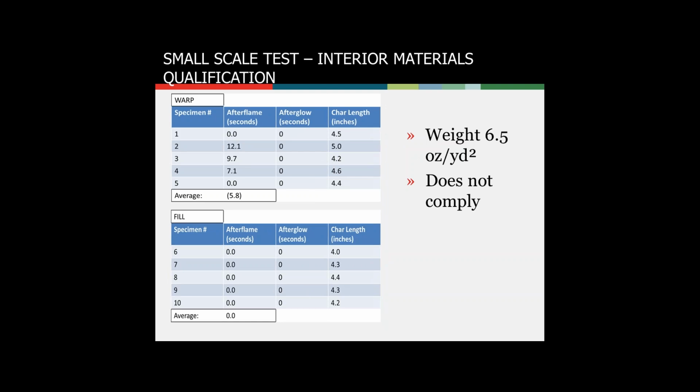This is a sample that failed the after flame. It had 5.8 versus the 4 seconds allowed. The char lengths were all good, but I think most of the failures we find in today's market are more related to after flame than char length.